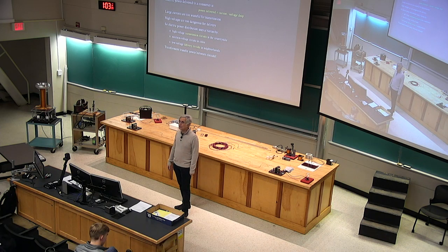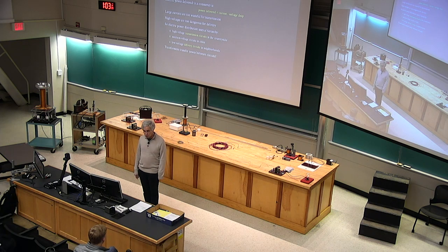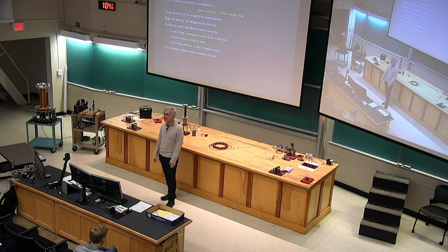And if you look at the power consumed by the wire itself, with a little bit of manipulation of the numbers, it turns out to be proportional to the square of the current in the wire. It's actually the resistance of the wire times the square of the current. So if you double the current in the wire, you quadruple the power the wire itself chews up. And this is a problem. It's a real problem that society deals with routinely.